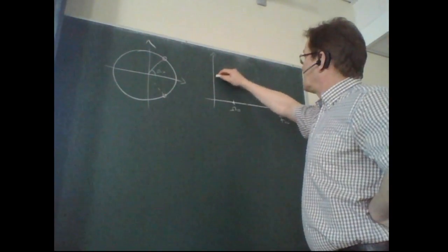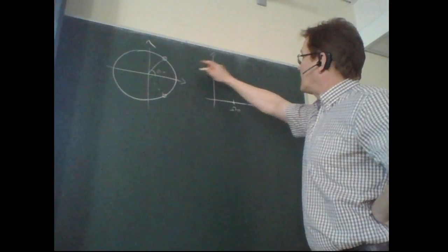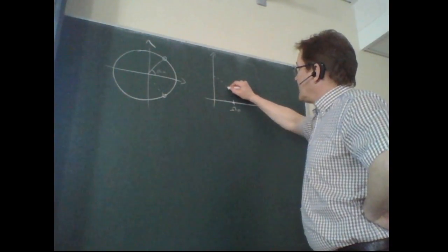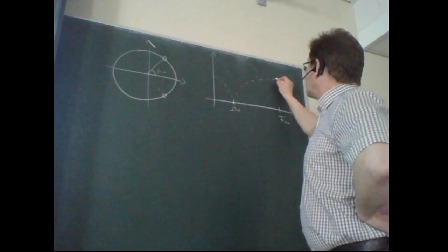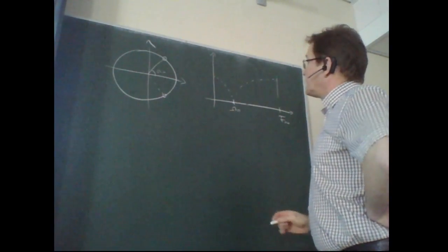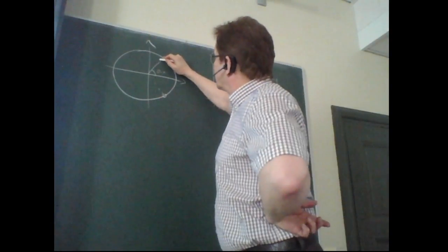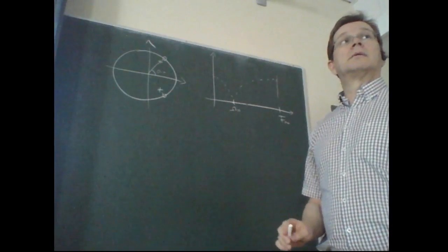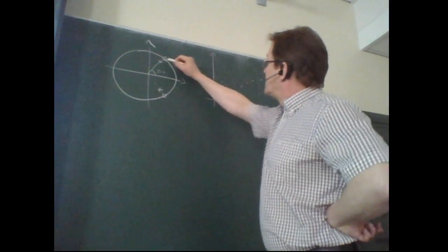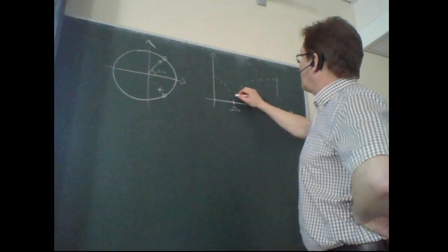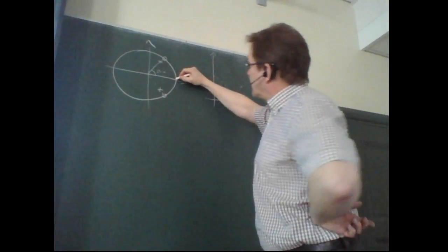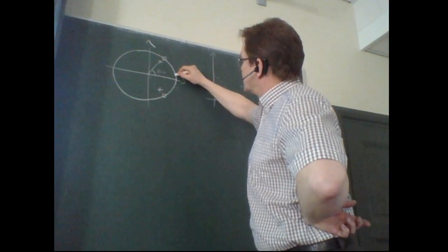Then basically, if we had only this one and all the poles on the origin, which would be an FIR filter, our amplitude response would be like this. However, if we put a pole pair on the same angle as our notch, we will actually get amplification on this region, and even better, think of a signal or frequencies around here.